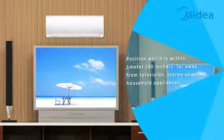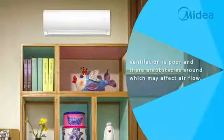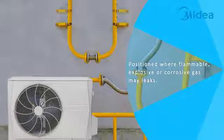Position which is within 1 meter, 40 inches, far away from television, stereo or other household appliances. Ventilation is poor and there are obstacles around, which may affect airflow. Position where flammable, explosive or corrosive gas may leak.